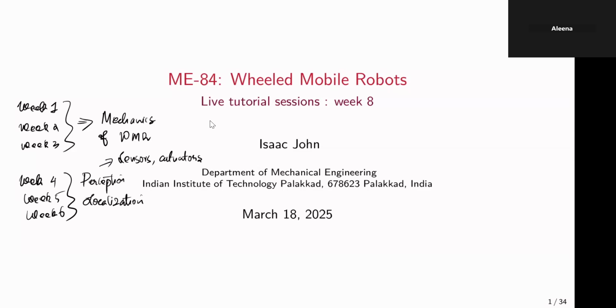Not only do we rely on the map data, we also rely on sensor data. We discussed two algorithms, Markov localization as well as Kalman filter localization, which essentially give a brief overview of how to fuse the data from odometry, or the predicted data, as well as the data from the sensors, to have a very good estimate of where the position of the mobile robot is.